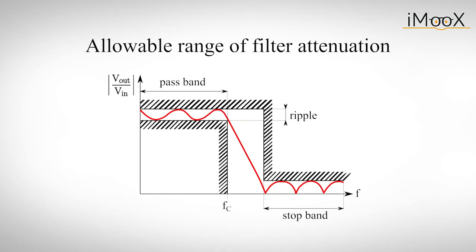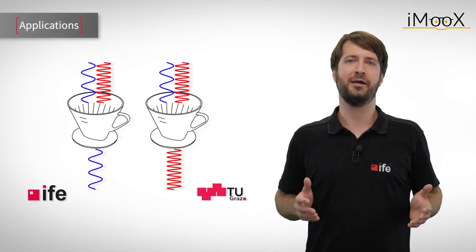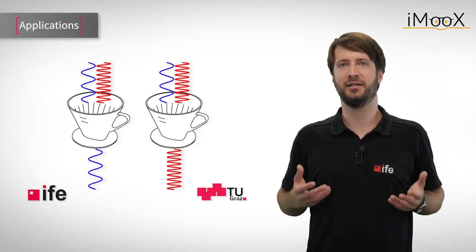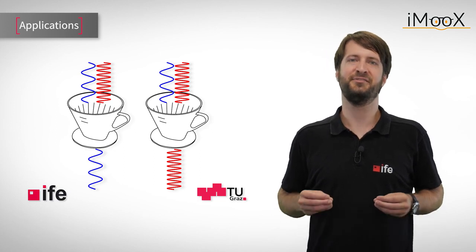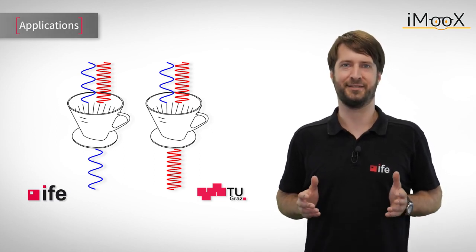Usually, all those demands will leave you with an allowable range of filter attenuation, which is often depicted like this. The graph shows you parameters which behave like borders for attenuation and frequency. For a satisfying design, they must not be crossed by the recorded frequency response. With all those requirements in mind, the numerical calculation of such a filter is a very challenging, if not depressing task.